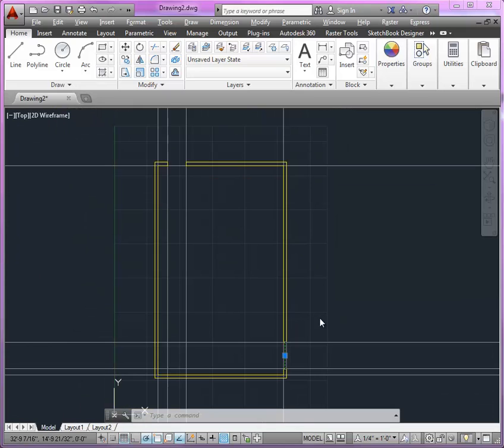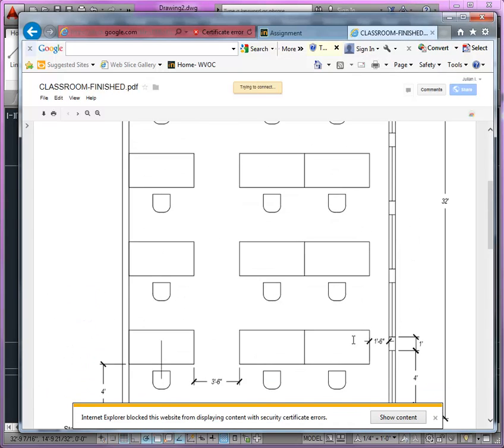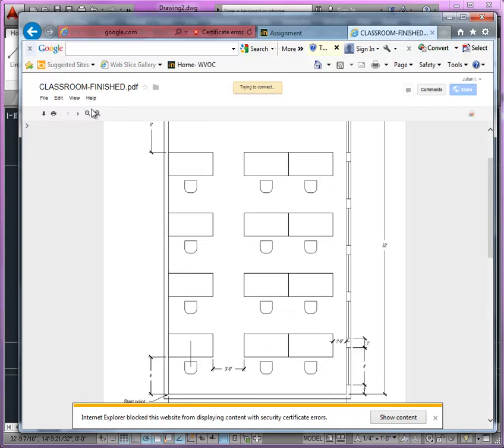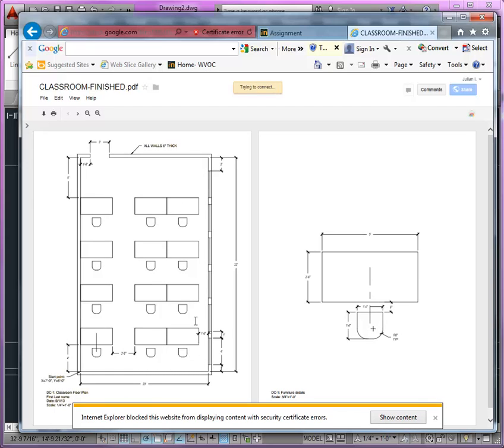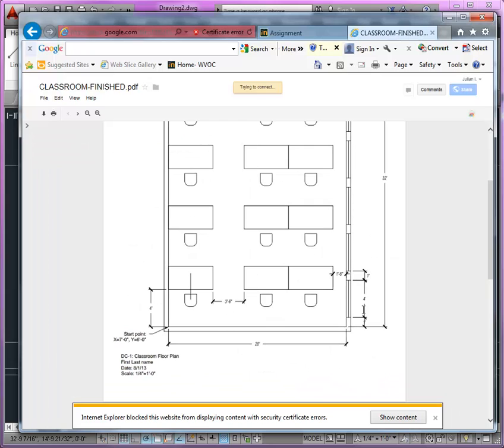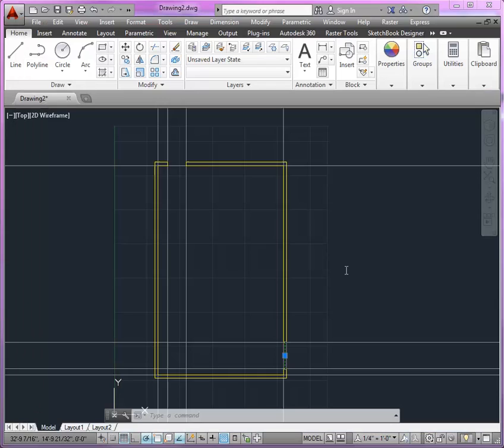We know, if we look at the drawing here, basically what we have here is, let's zoom out a little bit. Okay, we got 1, 2, 3, 4, 5, 6 windows, each spaced 1 foot apart from each other. So when you look at it, you could think of this as 1 column and 6 rows, right? The spacing would be the distance from the corner of one instance to the corner of the other instance. So that would be a distance of 5 feet, right? Let's come back to the drawing here.